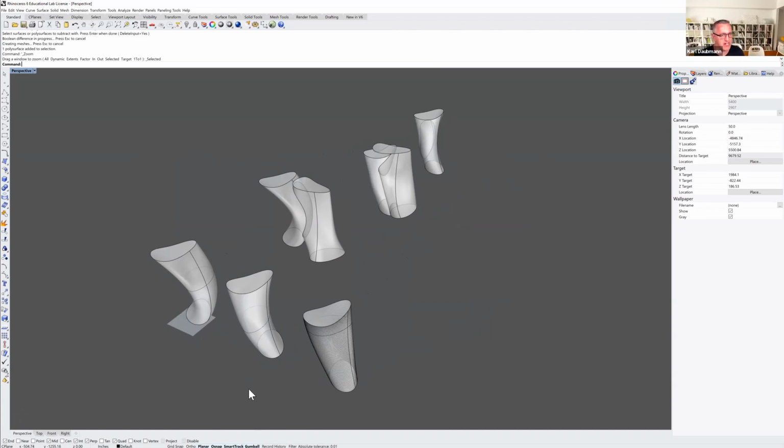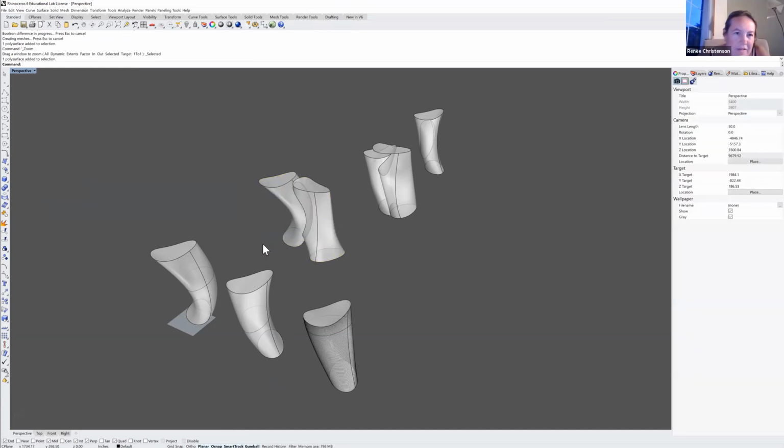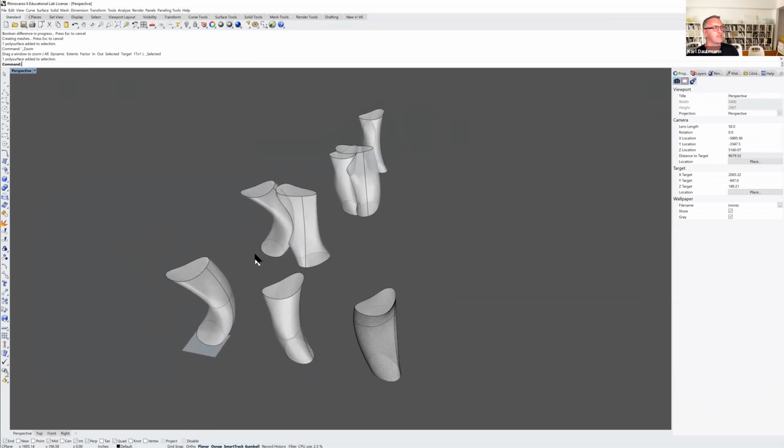Look down here at the very bottom. Okay. There's an option down here and it looks like it's bold or, oh, not bold. So see what happens if you click that and make it bold. See if you get it at that point, if it shows up. Let's see if I did it. It's bold now, yeah. That's the coordinates, right? The red and the green. And so that way, if you pull the red, it'll lock it in that direction. Or if you pull it green, it'll lock it in that direction. Or if you use the blue, it'll orbit around that center point.